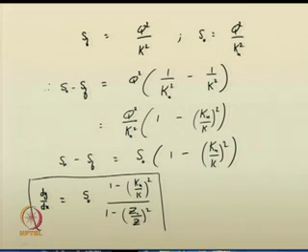So, I have now represented the dynamic equation using conveyance factors and section factors. Why I use this is that by knowing the conveyance factor and the section factor, you will be easily able to identify, based on the depth of flow, what type of gradually varied flow is there. This relation can now be used for classifying the gradually varied flow profiles, which is coming as a subsequent part of this lecture. We will see that.